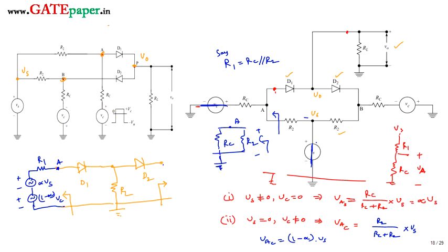So diode 2 can also be written in the same way. That is R1, whose value is Rc parallel R2. Next it is connected with alpha Vs with plus minus, and later minus plus with 1 minus alpha times Vc. So this is the Thevenin equivalent applied across both sides of the diode. Now the circuit has become simplified. We can calculate the gain.